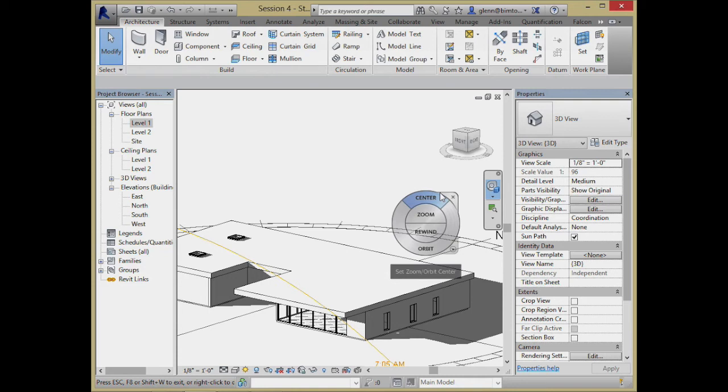Not sure if you can see in here. Because the sun is lower, just the angle with which it's hitting the building, it's able to penetrate the building in the wintertime, but not in the summertime. Stuff like that. So roof overhangs are one of the things we're going to play around with in terms of thinking about facades and how to deal with facades. It's a very, very useful tool to play with.